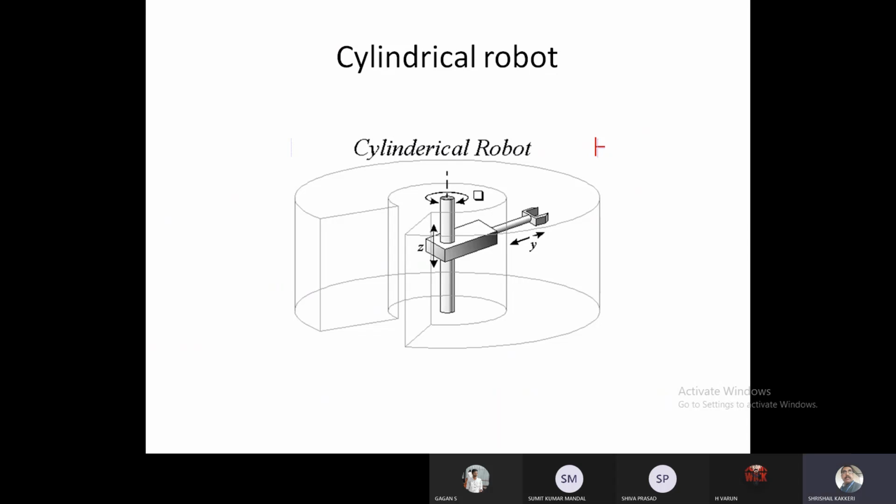And since the rotational joints are there, the independent rotations and flexibility will be more as compared to the Cartesian coordinate systems, so that it can remember more points and generate a required definite path. So the controller should be a very good one as compared to the Cartesian coordinate robot.